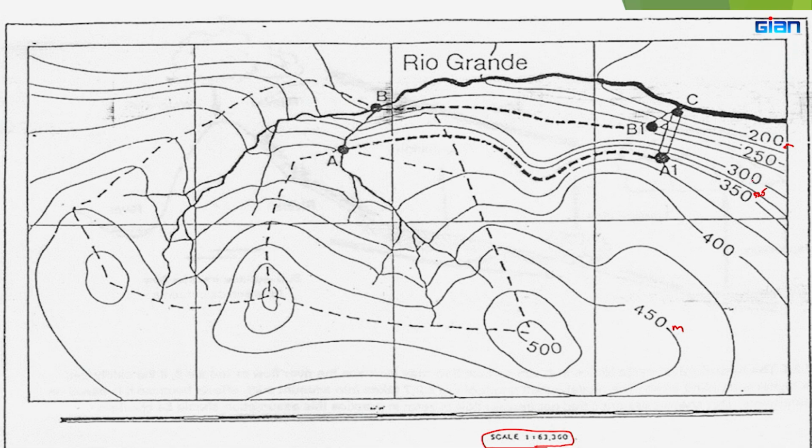So, it is a different scale used by a different survey authority, right. So, you will encounter many such small differences. The previous one, the height difference was 20 meters and here it is 25 meters. So, about the details it will be different, and when you do your own contour map for the site using a survey team, you can ask them, I want 10 meter height difference, or I want 5 meter height difference for my scale, because in order to plan your civil components, you might need that detail, right.